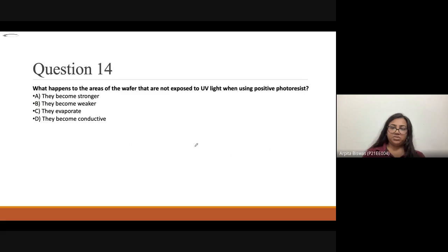If you see the structure, there is a wafer, and on the wafer there is silicon dioxide present, and if we go for some electrodeposition or the microheater, some metal is present. On the metal, if we want to do photolithography, we use positive or negative. Here we use positive photolithography. And there is a mask, where this portion is opaque, like this portion is covered, and this portion has this type of structure.